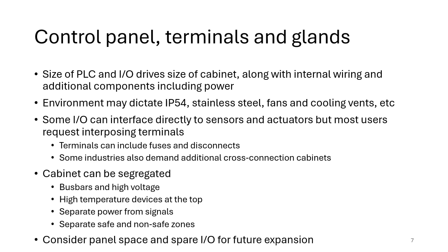It's also worth considering the panel space you use and allowing for spare panel space and also spare I/O modules to allow for simple future expansion. If you make everything too small, then of course you might save money initially, but you could make any future upgrades very expensive and difficult, even to the extent that you might have to replace the whole panel in future if you want to do any sort of upgrade.